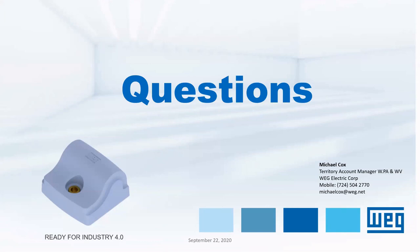But drilling a hole isn't going to damage the thermal dissipation capabilities of the motor, no matter whose brand it is. So I would say if somebody drilled a hole in the frame into the inside of the motor and damaged the winding, that would be a warranty issue. But I wouldn't see having our sensor or somebody else's sensor mounted onto somebody's motor causing any type of warranty issue.